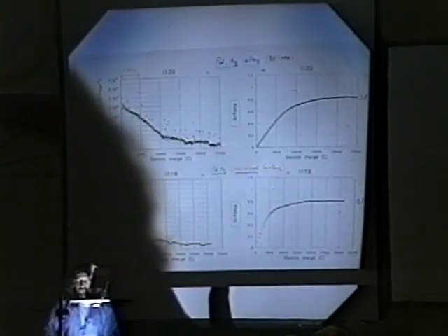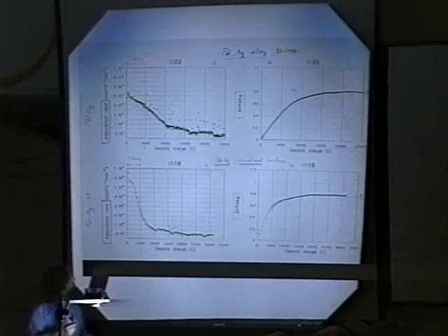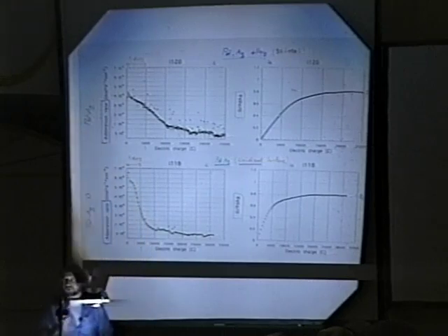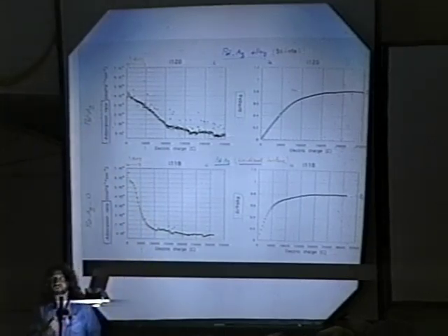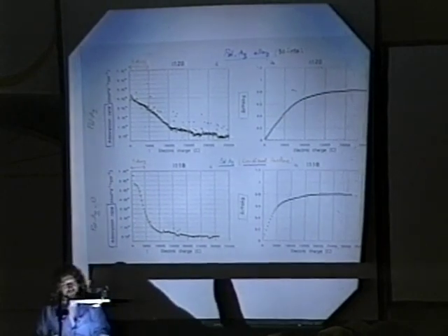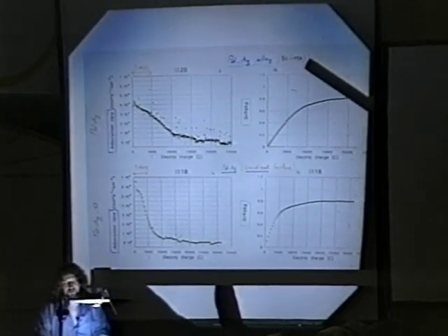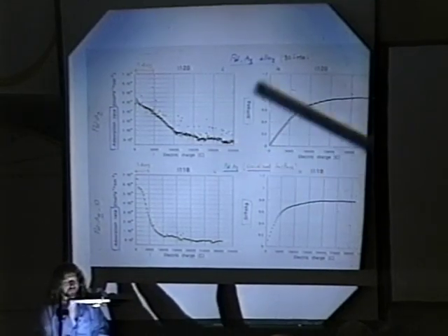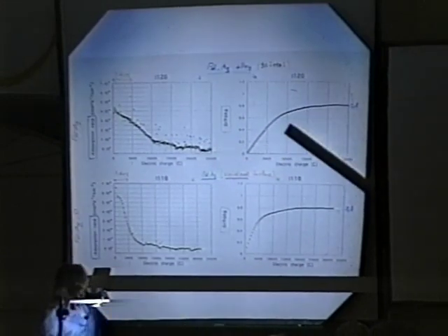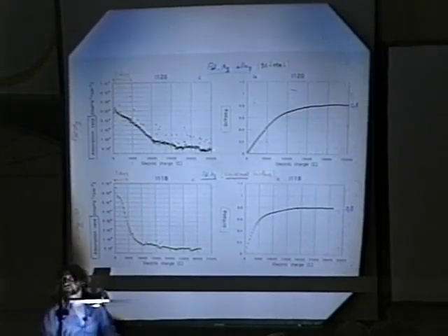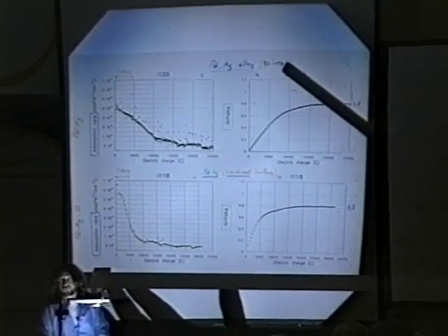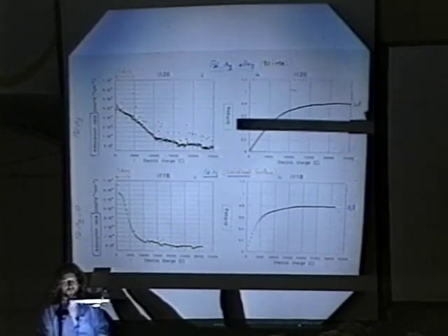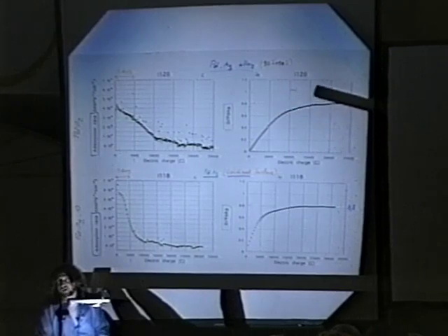Okay, we were interested to study some palladium alloys, and in a special way palladium silver, because this kind of alloy is very often used in cold fusion experiments. Silver is at 10%. This is a typical absorption rate, and the loading ratio reaches 0.8. Let's take into account we have 10% of silver. If we just normalize to palladium, we reach something like 0.9.